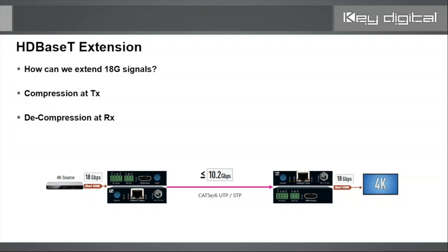And let me tell you, we're going to start talking about compression when it comes time to discuss our AV over IP, for example. And compression is, for the last year, 2 years, now a very real part of video signal distribution, signal management. When you do AV over IP, if you have a source that is 10 gigabit per second 4K, or even 18G, some systems may support, but you're going over a 1G network switch, you're going to have a compression factor there of 18 to 1, right?